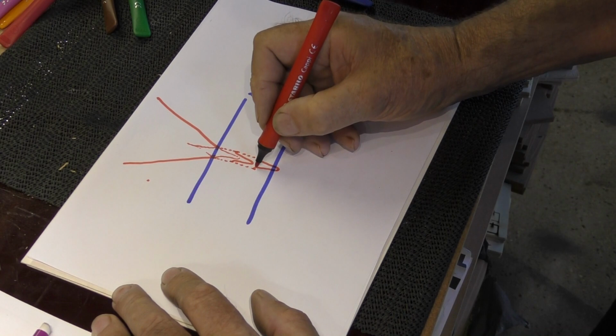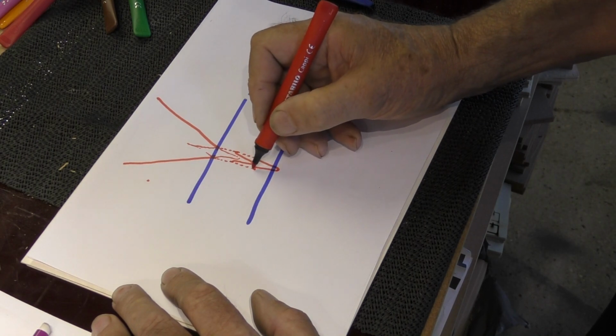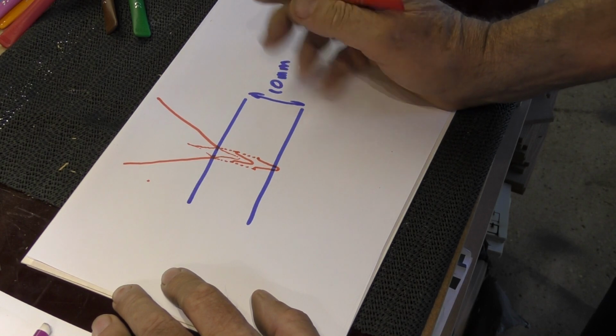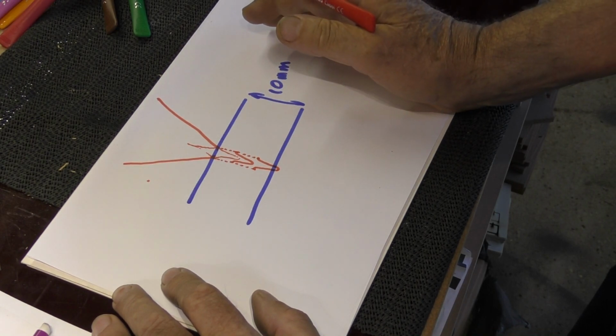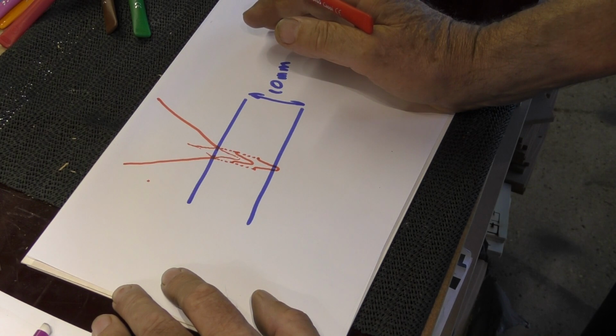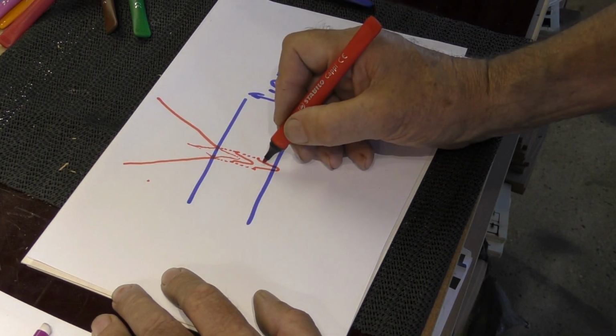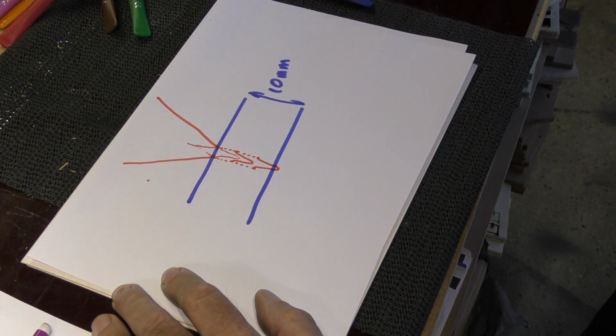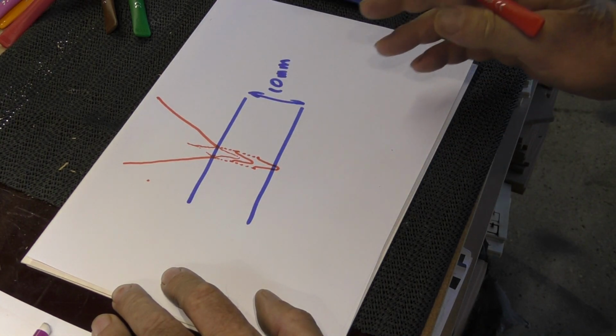But what we've also got left behind is the end of the point of the beam. I call it the point of the beam because it isn't really pointed, it's just got this high energy density centre part which is doing the most damage to the material. And once the damage has come out the bottom of the cut, you are happy to say, right, that's it, that's the right speed for cutting.